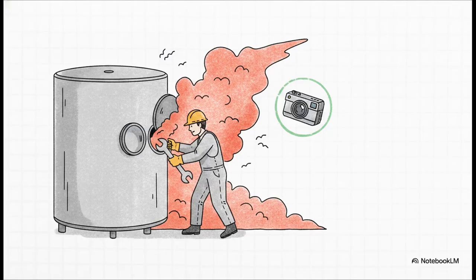And that ongoing competency is absolutely crucial, because an offshore platform is a living, breathing machine. Hazard zones are not permanent fixtures. Routine maintenance or opening up a tank can instantly change a perfectly safe gray area into a deadly Zone 0 red area. This is exactly why strict management of change procedures are vital, and why inspectors have to use intrinsically safe tools, like certified ATEX cameras, to do their jobs without accidentally becoming the ignition source themselves.